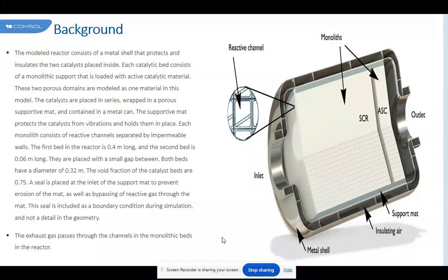The main results in this work are summarized here. The first one is a mathematical model. We consider a one-dimensional two-phase mathematical model of a straight channel washcoated catalytic monolith with the following assumptions. Conduction and diffusion in the axial direction are negligible in the fluid phase. The fluid flow in the channel is laminar, either fully developed or developing. The pressure drop in the channel is small so that its effect on the concentration and velocity may be neglected.